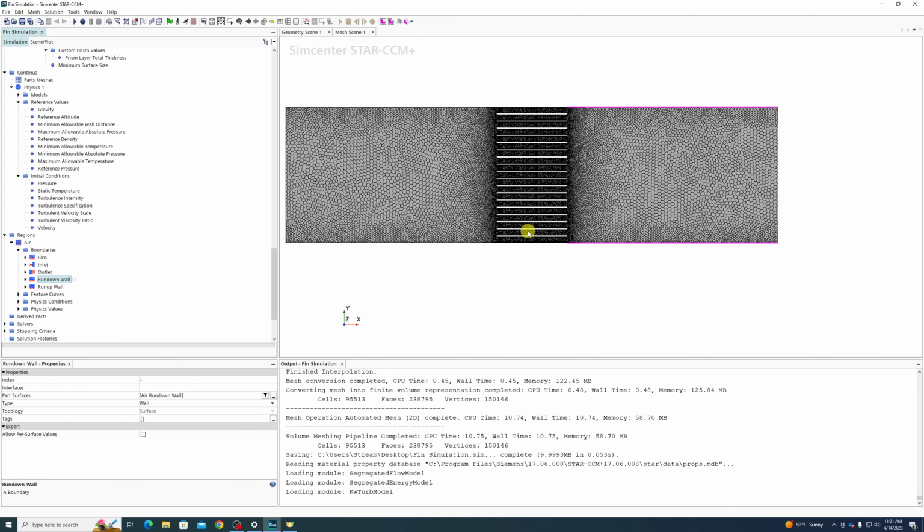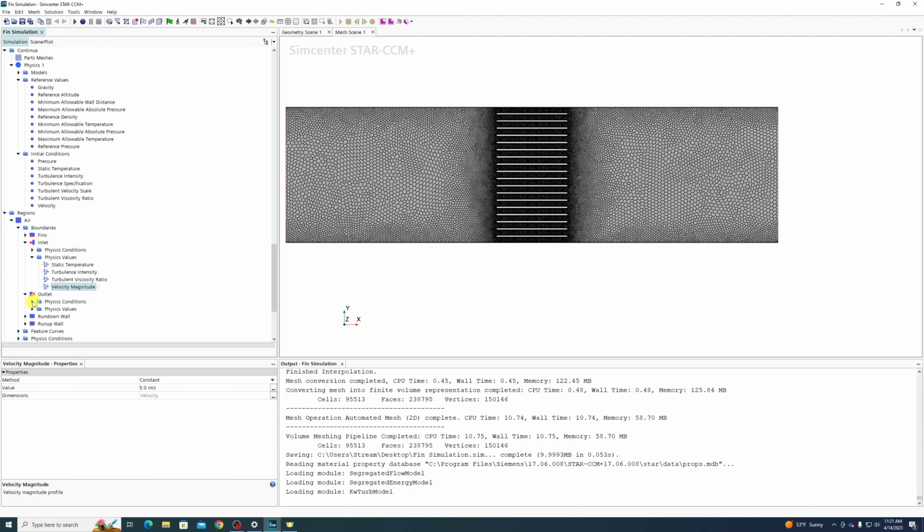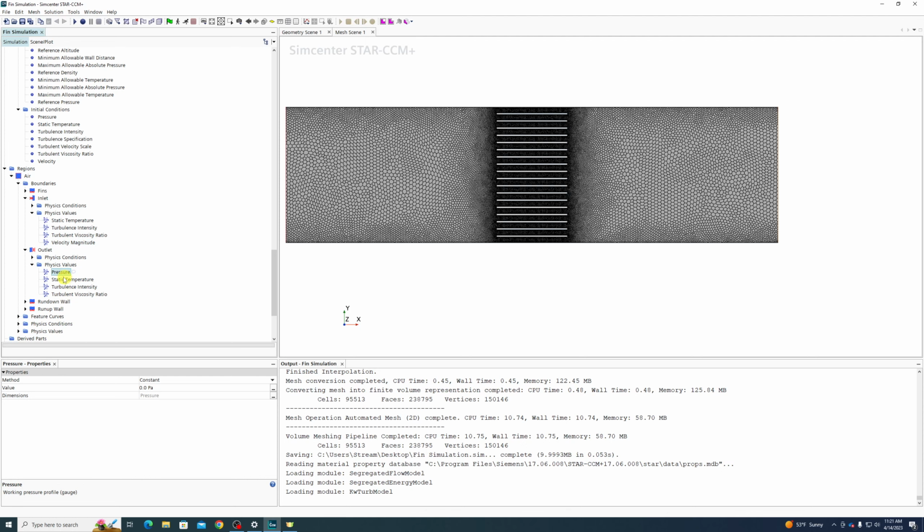So the only thing we're really going to change here thermally is our inlet boundary condition. It's going to come in at 300 Kelvin. That's fine. It's going to come in at, what's a good number? 5 meters per second. How about? Not super fast, but definitely not super slow either. Outlet pressure is fine. This outlet pressure and temperature is only going to matter if flow comes back in through here, so that should be okay. These can be adiabatic walls. That should be fine.